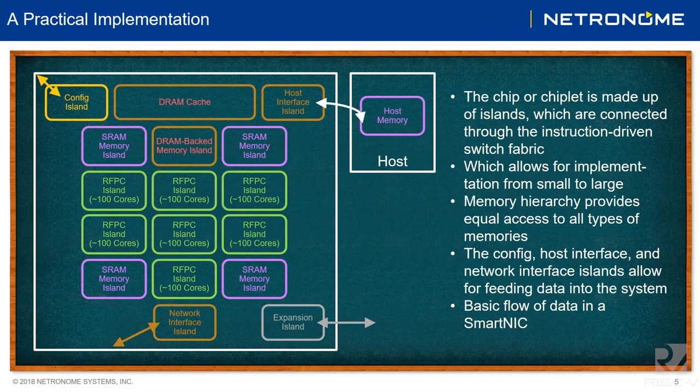I don't have time to go into all the processing that happens today, but I'll just say there's a big magic block there that works on the packet and determines what to do with it, whether it has to be encrypted or decrypted, and what's next for the packet. Eventually the processor determines the packet is finished processing and has to egress the system somewhere. It will send a command through a transactional memory unit to schedule the packet for the appropriate egress port, whether that's a host port, a network port, or further processing on another processor within the same chip.